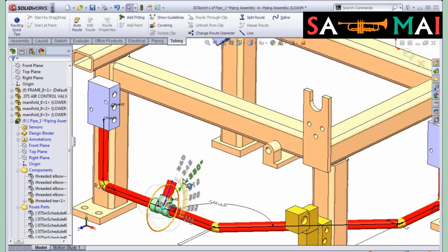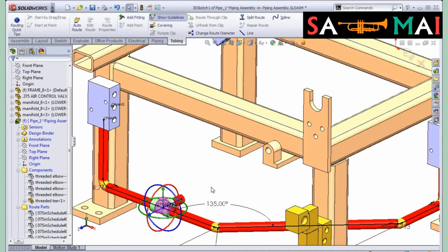And there's a compass, or a protractor, whatever you want to call it, an angle here that you can set, and set this to anything. So I want to go to 90 degrees. So I'll snap to 90. Those are your 2 ways, either using the tab key or using that triad.